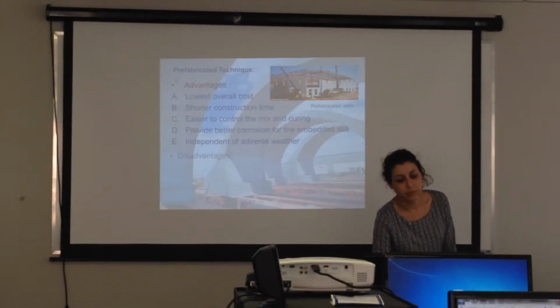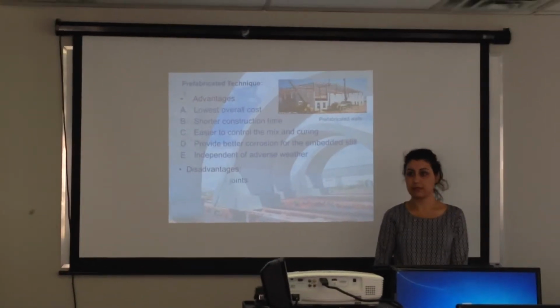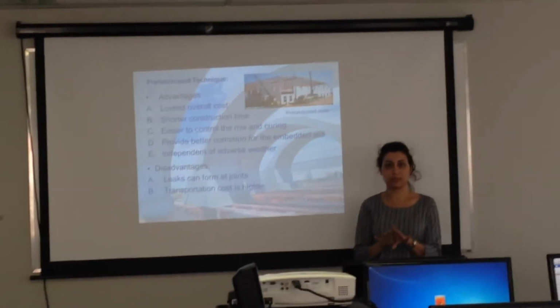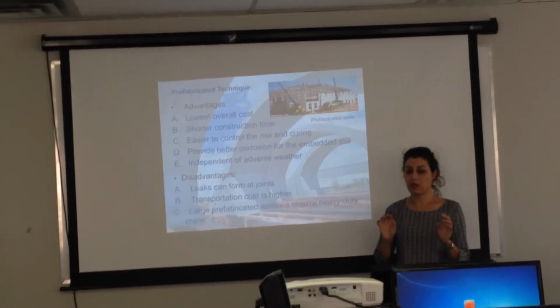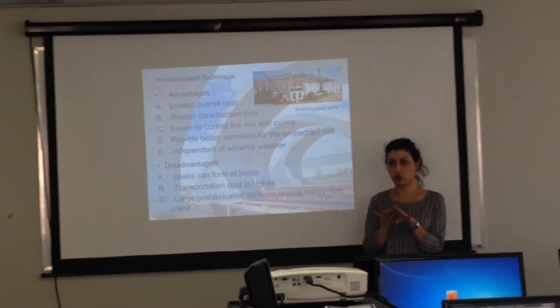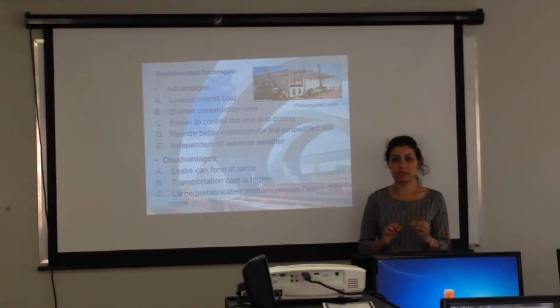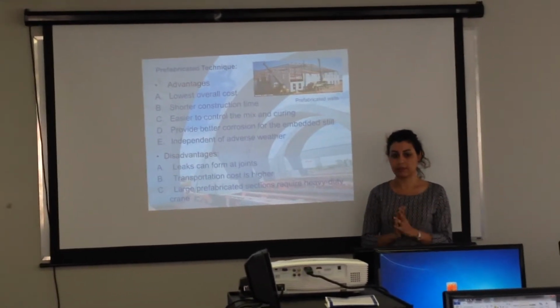But besides the advantages, it has some disadvantages too. For example, when we assemble the precast elements to each other, there is the danger of water leaking from the joint. So we need very specific details for the joint to seal it.